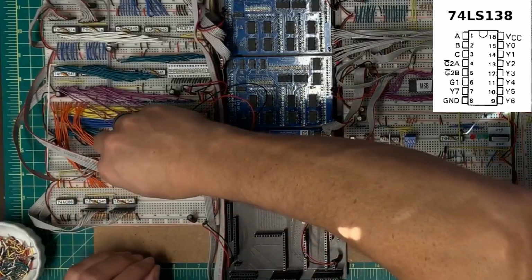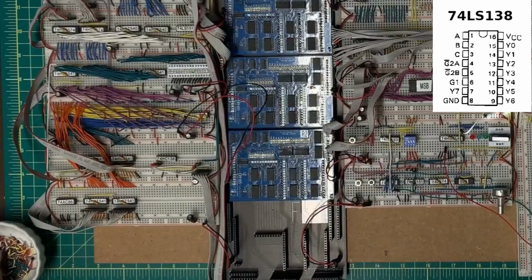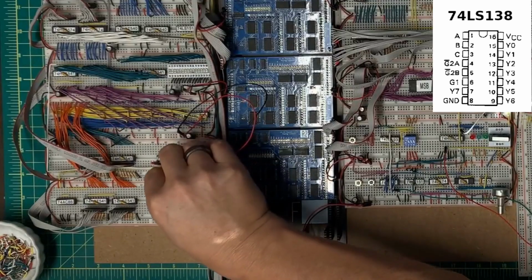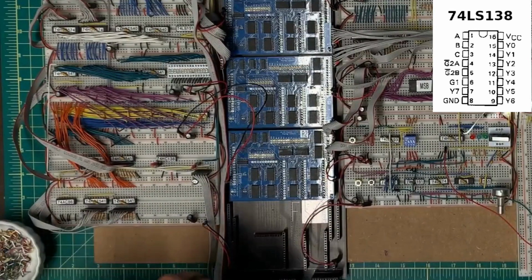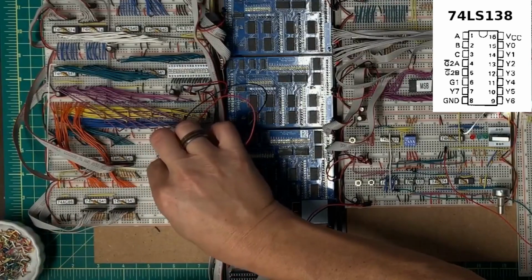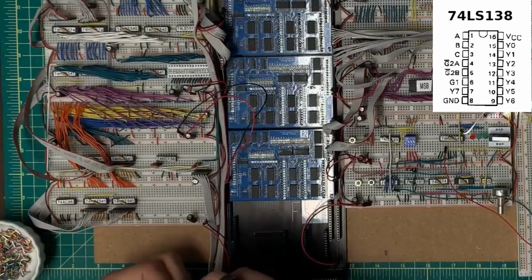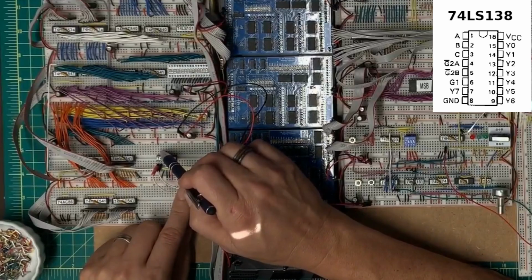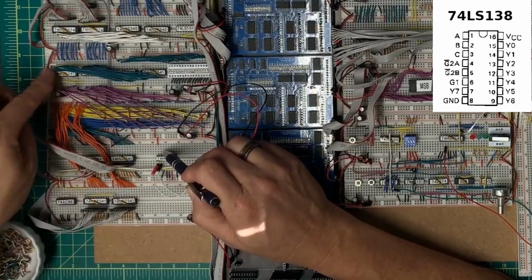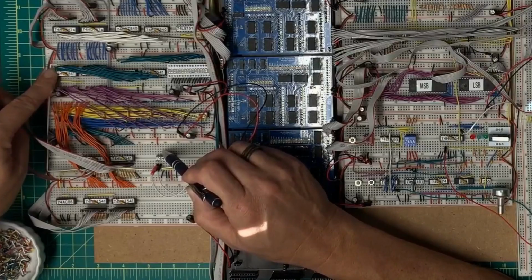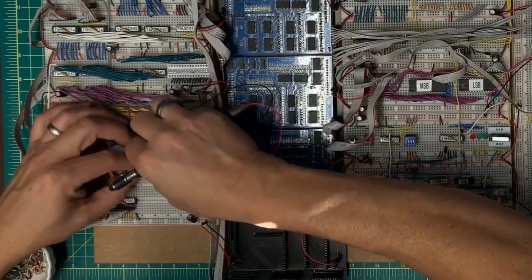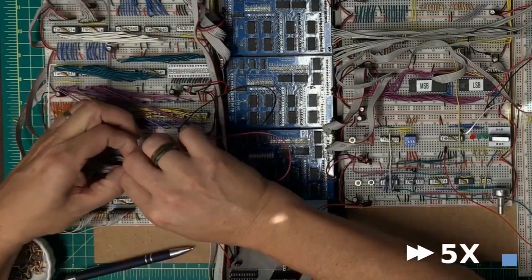Let me move this over to the other side. And then I've got 3 enable signals that I've got to handle. One is an active high signal. That's going to be pin 6. 2 of them are active low signals. It's pin 5 and pin 4. Now the output signals are going to be 0, which is do nothing. Pin 1, which is going to drive the line driver up here. So this signal here needs to be relocated up here to plug into output 1.